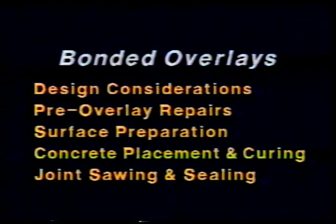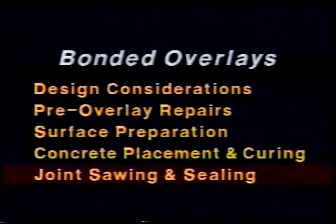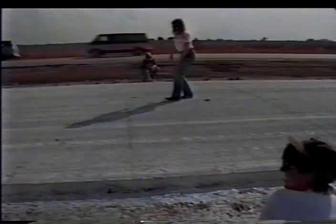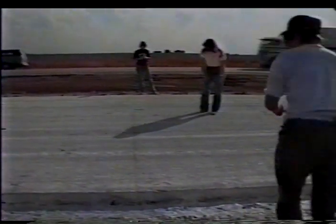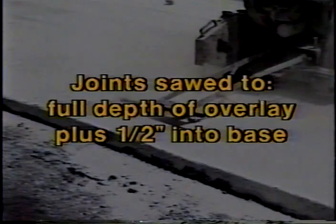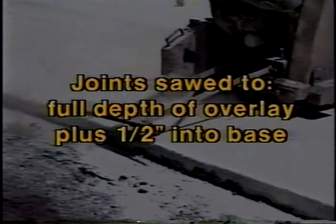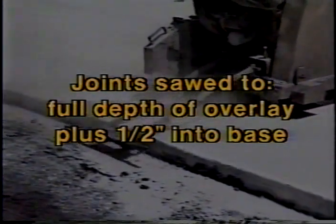And that brings us to the last steps: joint sawing and sealing. As with any concrete paving, the joints have to be sawed as soon as possible. The saw cuts have to be made directly over the joints in the base slab. If the overlay thickness is 4 inches or less, the joint should be sawed to the full depth of the overlay, plus an additional 1/2 inch into the base slab to ensure that the full thickness is cut.